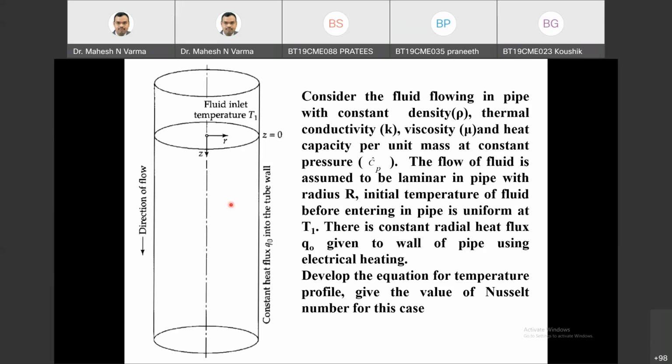Sir, second order conduction. How, Kaushik? Because we have solved so many problems in conduction in the R direction. First of all, one differential equation will come from the shell balance, and another differential equation will come from Fourier's law of heat conduction. So it will be a differential of a differential. So it will be second order with respect to R.